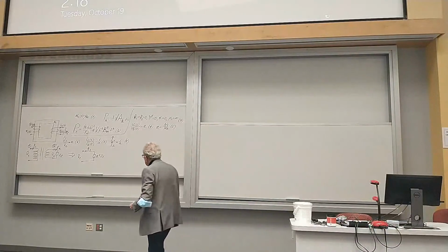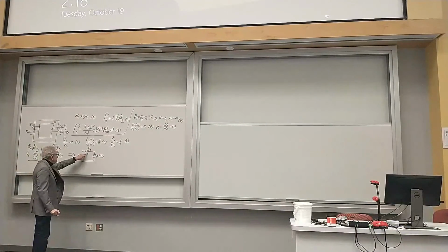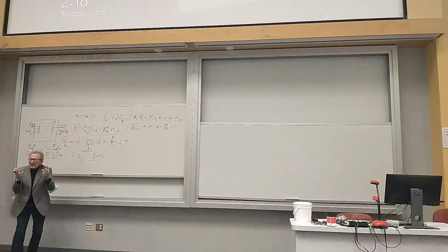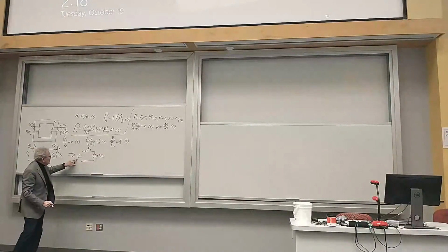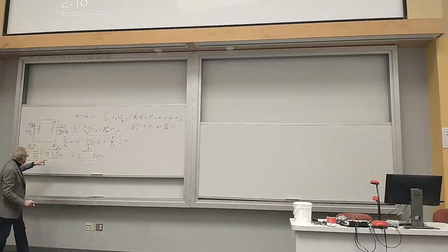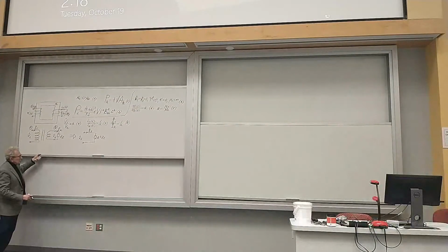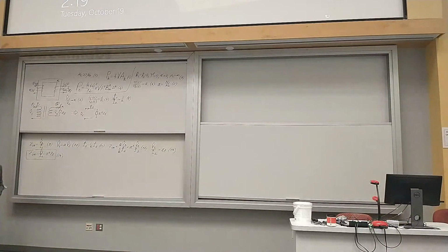They're the simplest object of electrical engineering. In what sense is it an equivalent circuit? V sub 1 and I sub 1 in this circuit have nothing to do with the actual physical design of the transformer. It's a circuit. But V sub 1 and I sub 1 are related with the same relationship as in the transformer, because it gives the expression for the input impedance. And the input impedance is a ratio of V sub 1 and I sub 1.